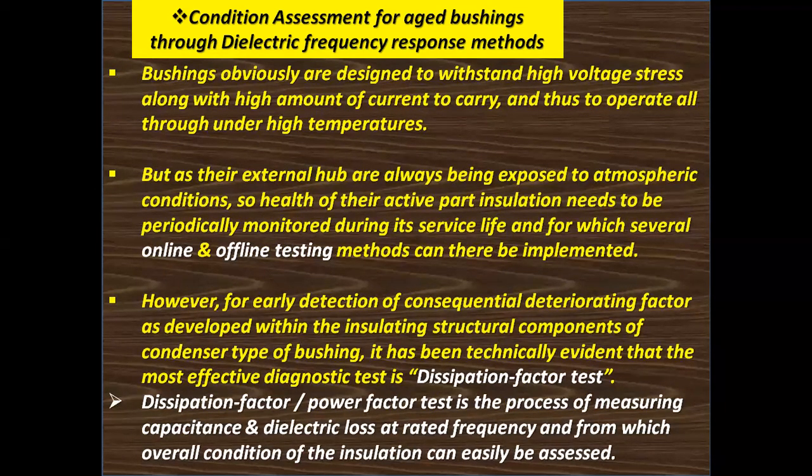However, for early detection of consequential deteriorating factors developed within the insulating structural components of condenser type of bushing, it has been technically evident that the most effective diagnostic test is the dissipation factor test.